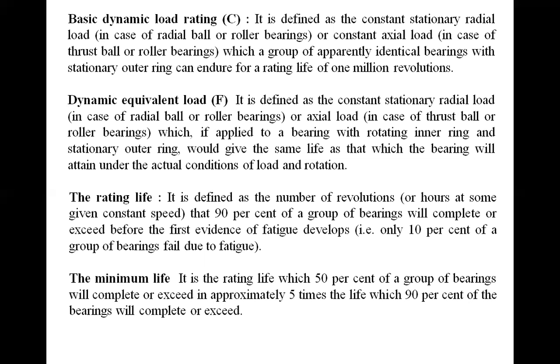Okay. So the median life is the life which 50% of the group of bearings will complete or exceed, approximately 5 times the life which 90% of the bearings complete or exceed. So that means here the number of revolutions completed by the bearing is very important.